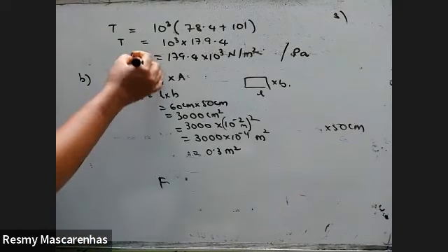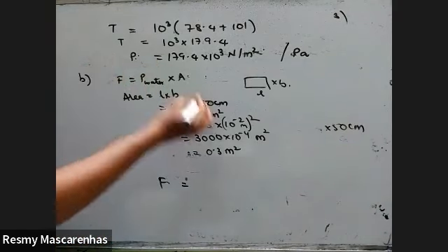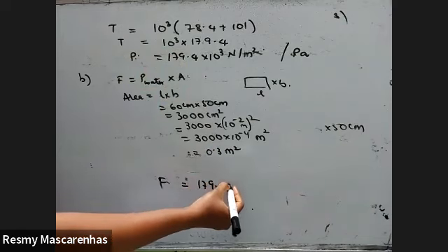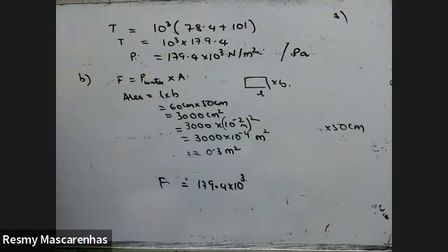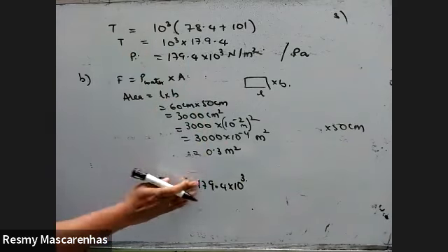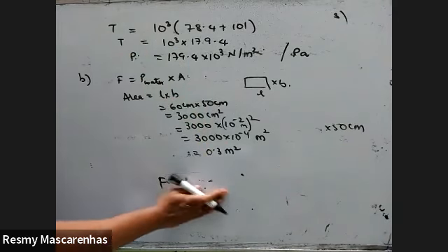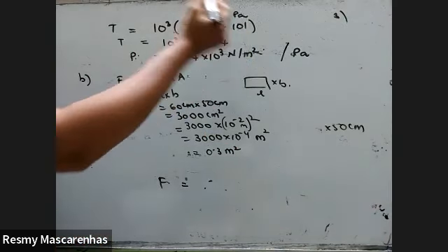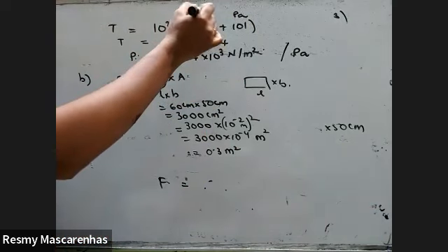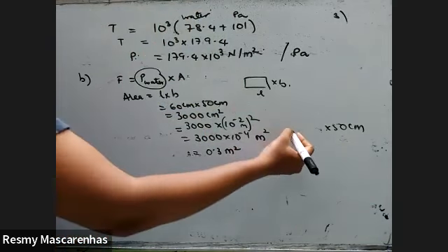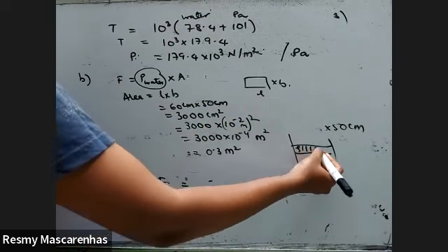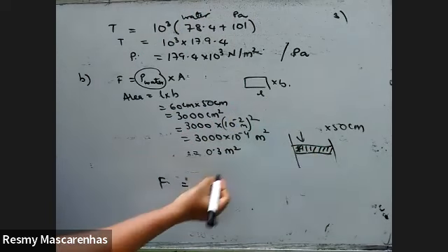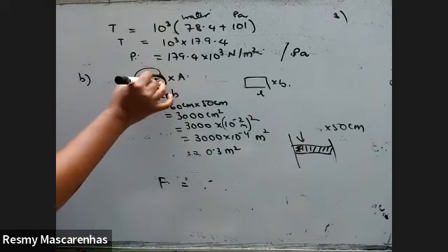Force. Put the pressure here. Oh, this we cannot take. This is the total pressure now. Only this has been asked because of water. This is atmospheric pressure and this is due to water. So we cannot take atmospheric pressure. You cannot take it because they've specifically asked only of water.